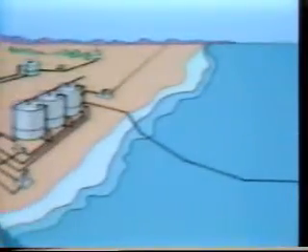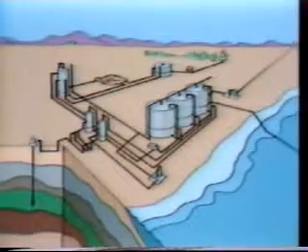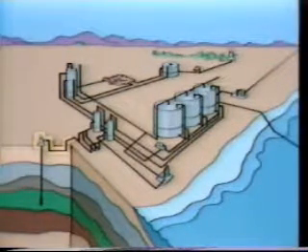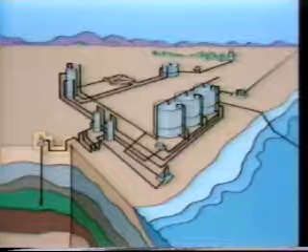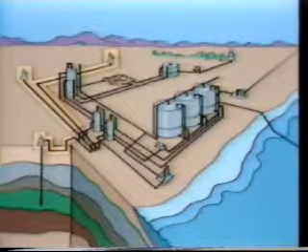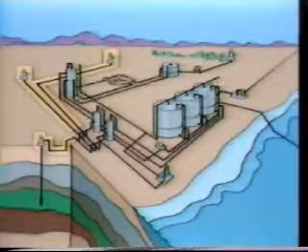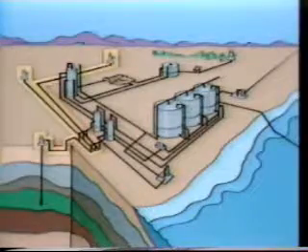Let's follow the path of produced fluids from the wellhead through the various surface facilities to the point of sale. The produced fluids leave the Christmas tree and enter a surface flow line system, usually a 2 or 3 inch pipe, which may be on the sea floor for subsea completions or below or above ground at onshore installations. If the production facilities are shared by a group of wells, as is often the case, the flow line will probably connect to a header or production manifold.